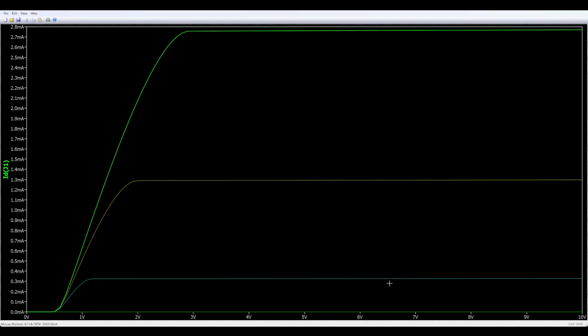All right, here's our plot. So basically, each of these is a different gate voltage. And here's our gate voltage down here. And then the plotted lines would be, I believe, the source. So you'll notice at 0, there's pretty much no current. But as we get to, I should say the plot, sorry, the plot is the current of the drain of the JFET.